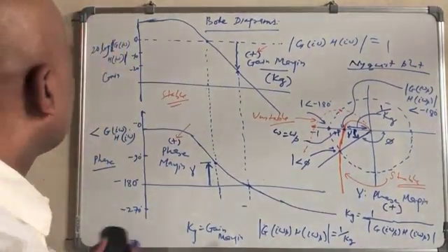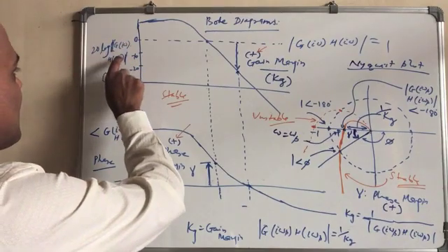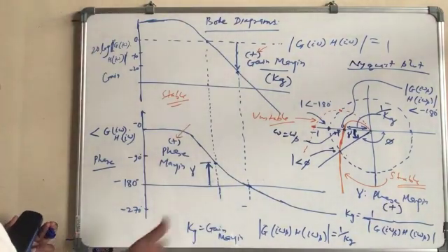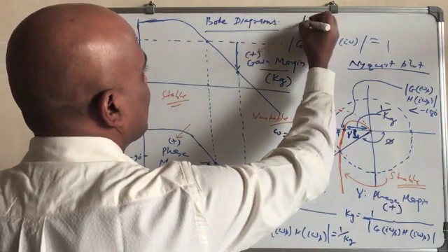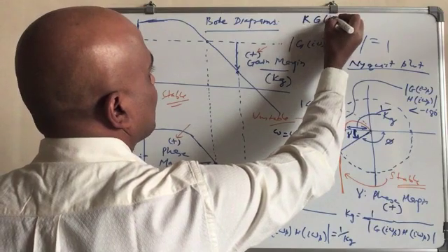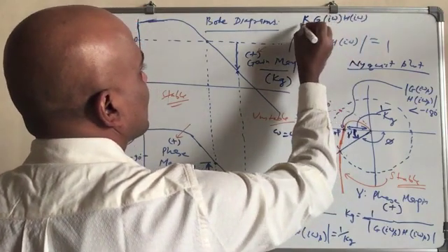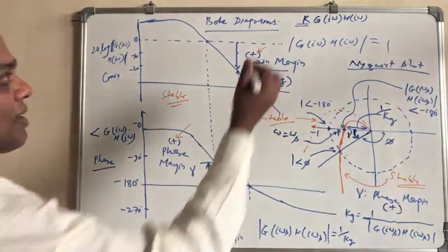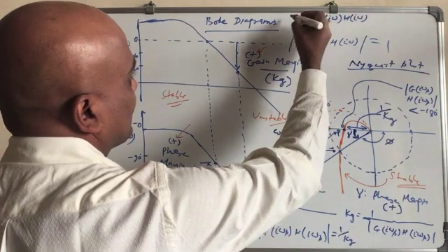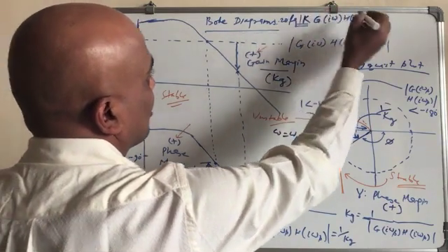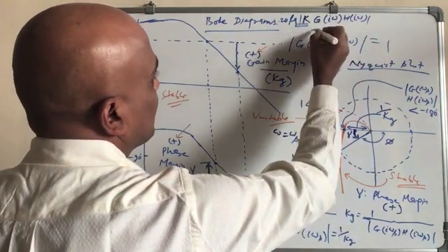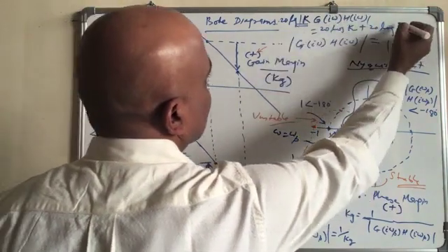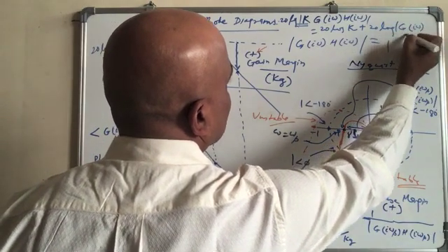Now the question is, if you are given G(iω)H(iω), for that you have the Bode diagram which is plotted like this. Then somebody asks, what about the Bode diagram for k times G(iω)H(iω)? You are just multiplying with k, so you can guess what you have to do is 20 log of that. It will be equal to 20 log k plus 20 log of the original G(iω)H(iω).